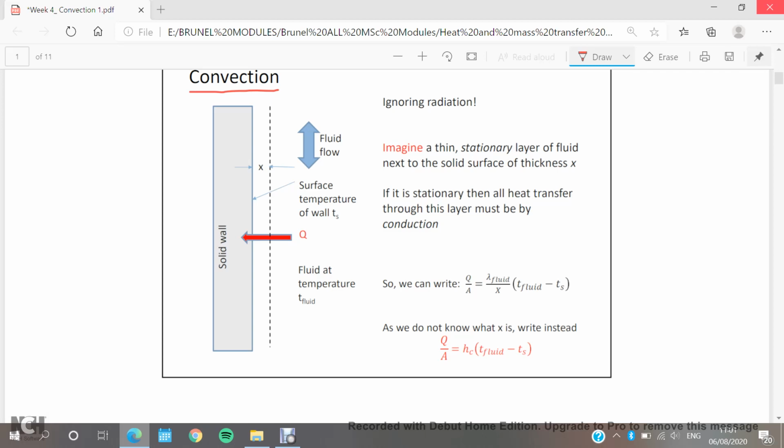As we mentioned earlier, our objective is to find Q, the heat transfer rate, as a function of delta T, the temperature difference between the two surfaces, and we want to put here something called U. In the case of conduction, we said U is called the U value of conduction heat transfer, and that this U is equal to the inverse of the thermal resistance, correct?